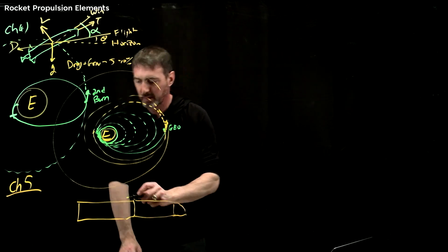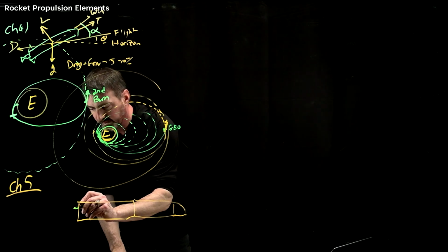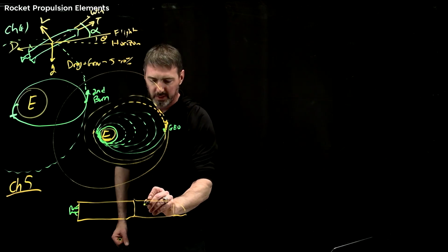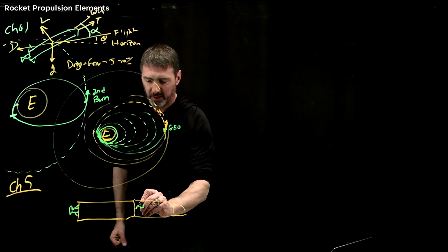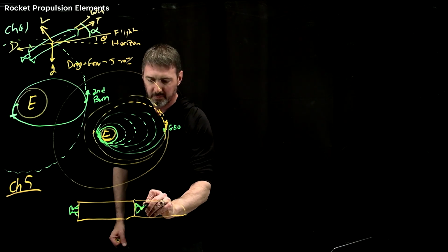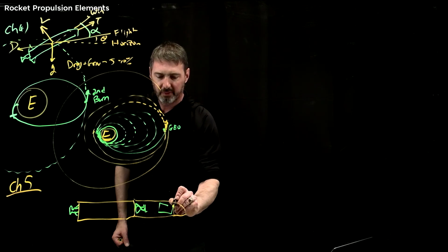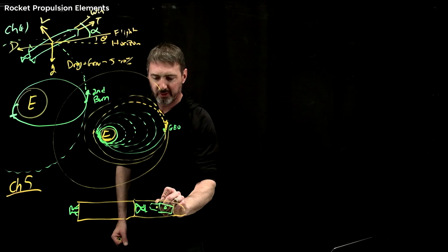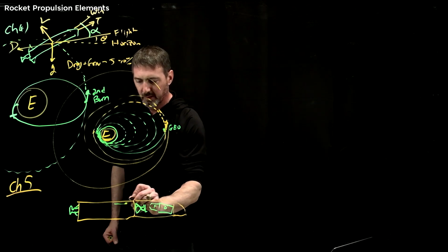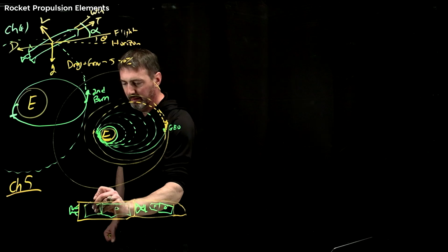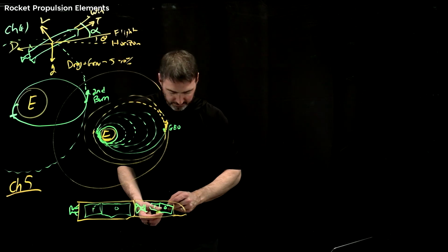All right, so you have, say, a rocket engine on the back, doing its thing. As I mentioned, it's got a gimbal. Here's your second stage. You've got a rocket engine here, usually with a bigger nozzle. And then usually up front is your oxygen tank, because oxygen is heavier than the fuels. And this would be, again, say, an oxygen tank and a fuel tank.